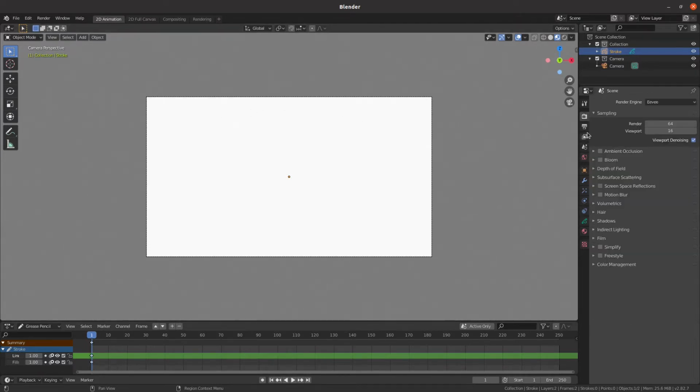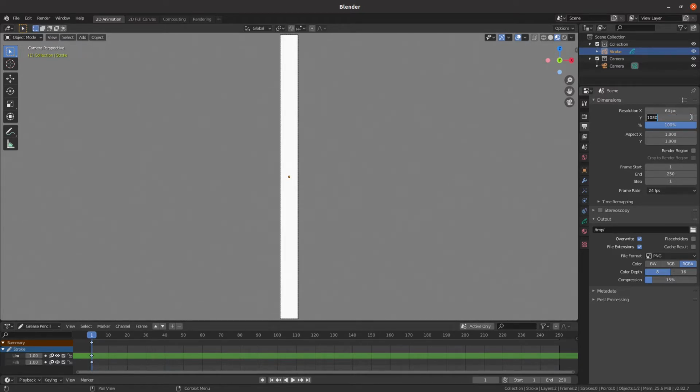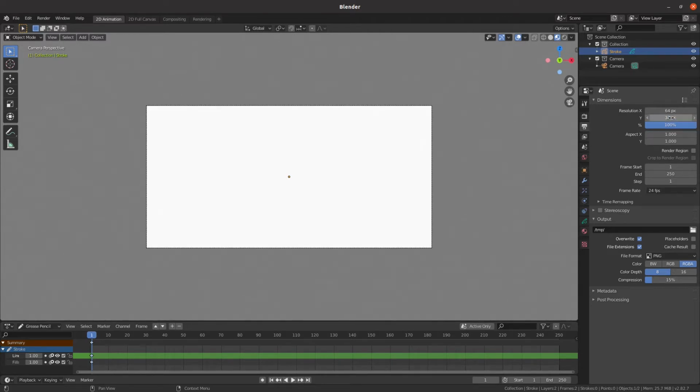I'm also going to set my render options. So here it shows 1920 by 1080 standard HD. For most people that's probably what you want, but for the matrix animation it's a very low resolution. It's 64 pixels across by 32 pixels down, so literally 64 LEDs by 32 LEDs. The output is set to /temp. We can put that wherever we want, and I'm going to use PNG files and RGB.